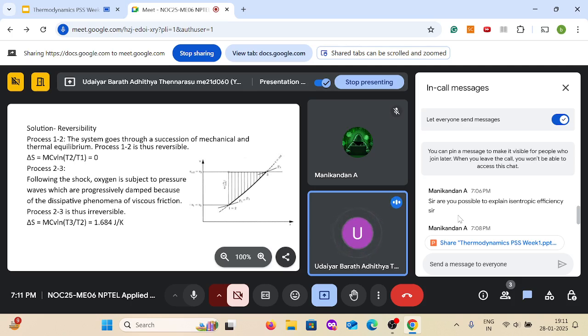But in the practical case, that doesn't happen. You have bearings, there is friction there, and there are valves and other things. If you have a piston compressor, your surface is in contact with the cylinder. These all add up friction, and your fluid itself will have its own friction, viscosity and so on. And there is heat transfer. So there are multiple phenomena, each comes into play, and they generate entropy. So this isentropic efficiency is an